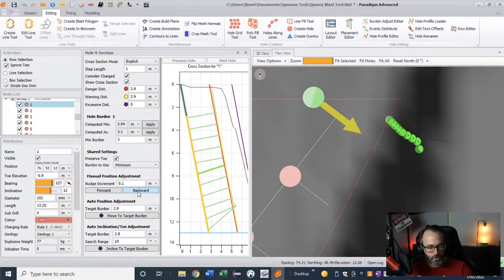So straight away we're going to write down somewhere on a sheet our chainage at 0, and we've got 1.4 behind, right? So 1.4 behind. That's how we're going to manage that blast hole and that angle. So this is how we would design for a quarry shot.